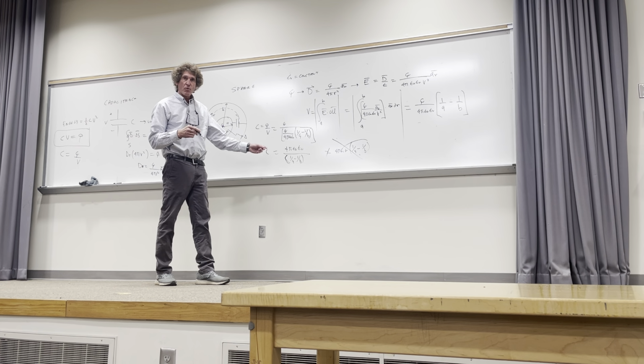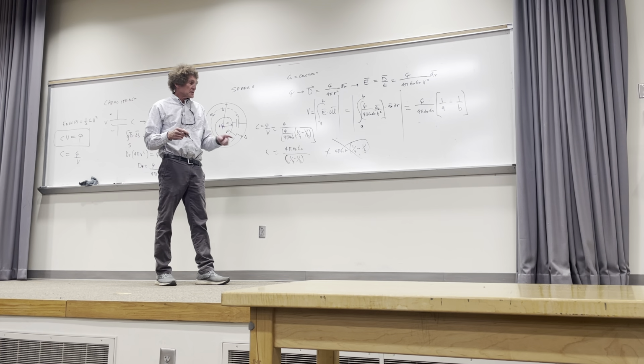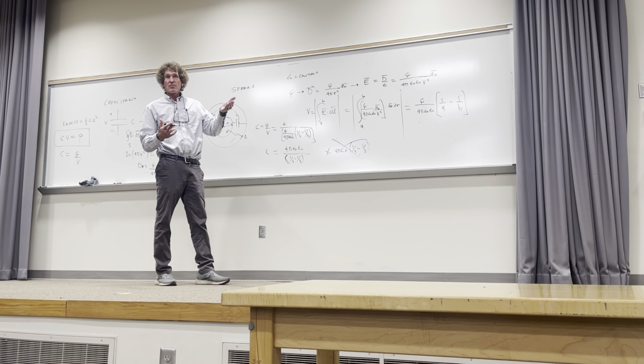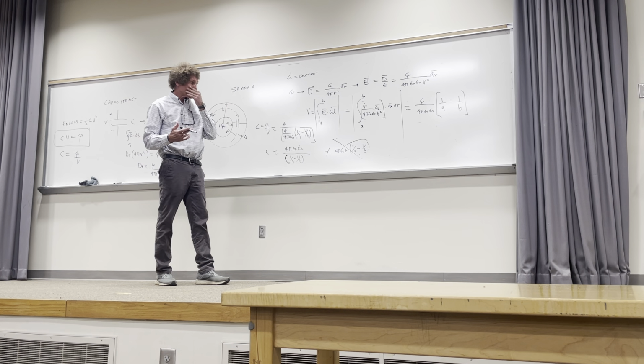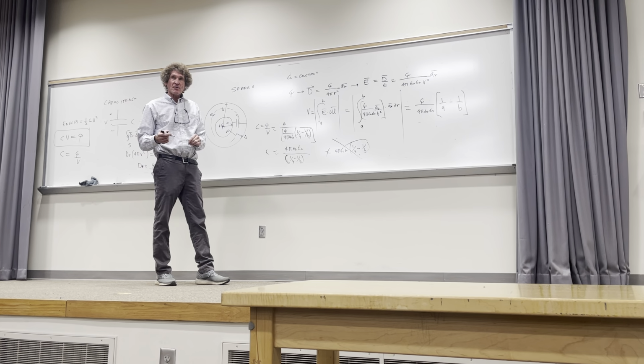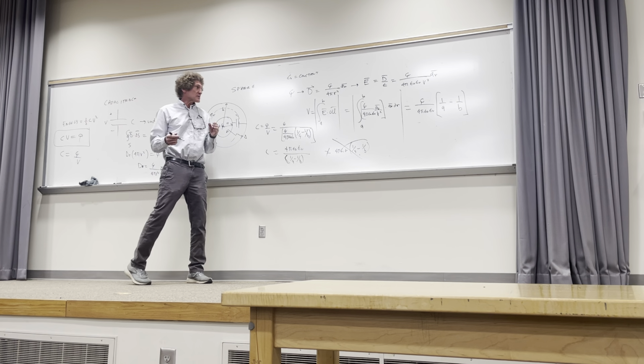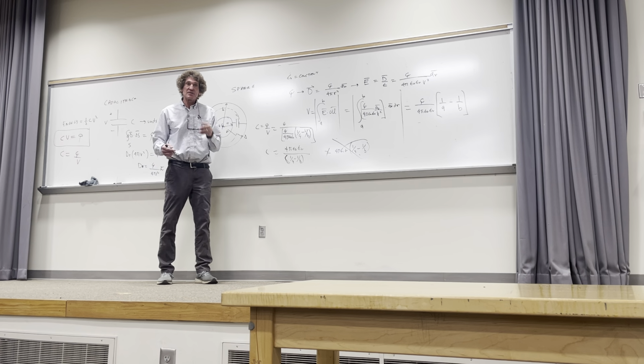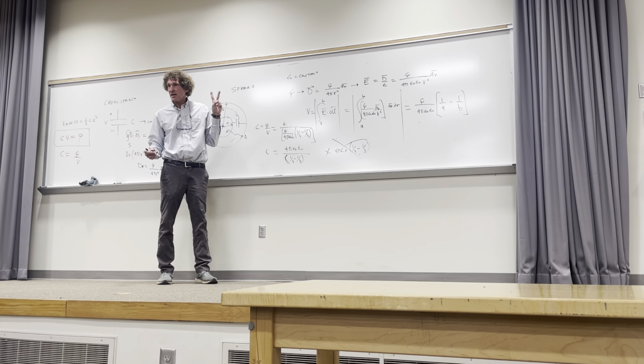Now, something that's always true with capacitance. Capacitance is always proportional to epsilon relative. You see how epsilon relative epsilon naught, or really I should say epsilon, occurs in the numerator? All right, it's never proportional to 1 over epsilon relative of the material, the dielectric materials. That's always true. As a matter of fact, one thing that becomes apparent is if we have this geometry with inner radius A, outer radius B, if we want to double the capacitance but don't want to change these dimensions, we just find a material that has twice epsilon relative. Do y'all follow me on that, class? And that's really important to appreciate the fact.